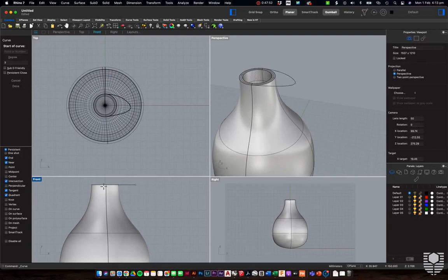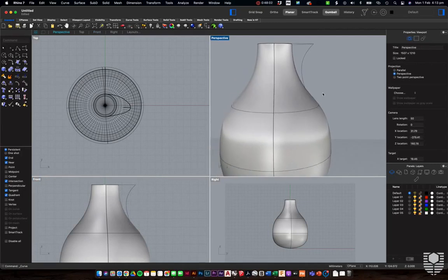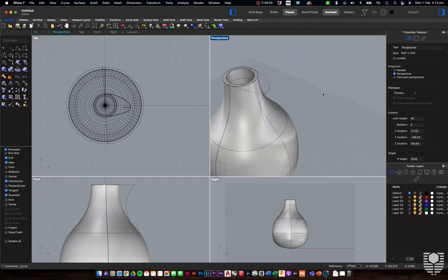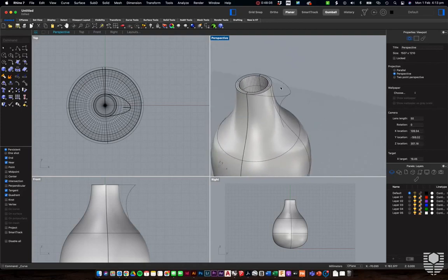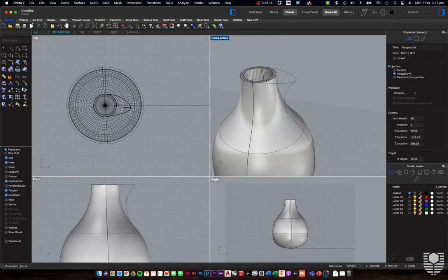This time we want to lock out to our quadrant, back in, a little bit more, and then down onto our surface there. And then we finish, and we can see that that was locked in to that plane that we were working on the side as well. Now we'd be able to use some of our surface tools to create the surfaces required so we can start manipulating this jug so that it matches up with our spout.